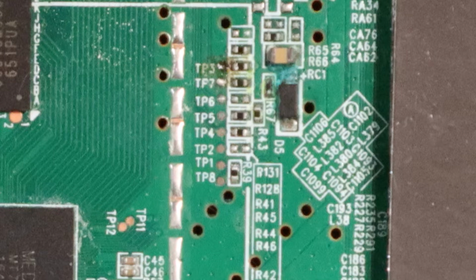Probably in our sample board the JTAG interface is available on some of these test points, but these pads are very small. I do not have any bed of nails tester, and I am not so good at soldering wires on such small pads. This means that I am not able to find the JTAG interface on this board.